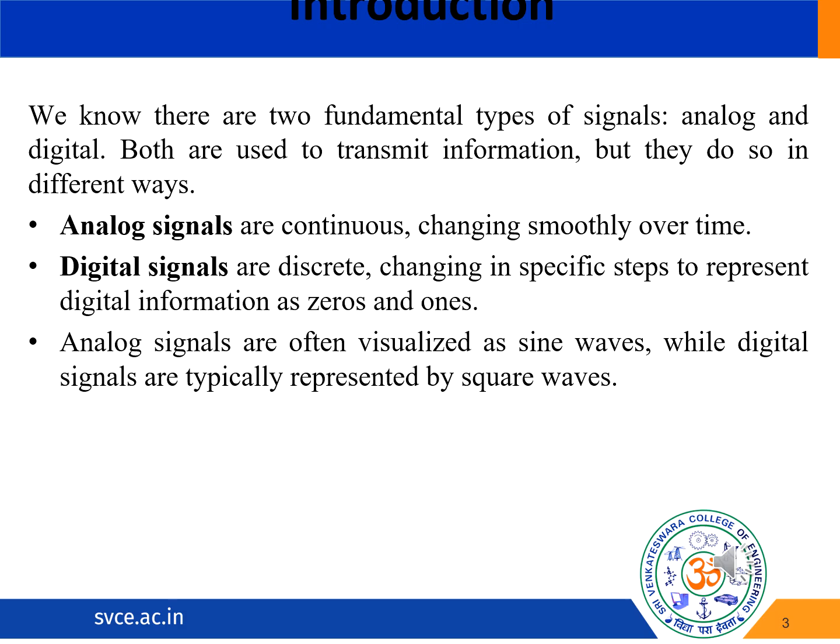So signal range, considering the signal range, is the range of voltages from minimum to maximum that can be passed through a switch. So the injection of a small electric charge into the signal when the switch is turned on causes a small spike, or we can call it a glitch. So this is the switch's ability to block signals when it is off. So this we call feed through. So parasitic capacitance can allow higher frequencies to pass through, making the switch appear to be in the on state.